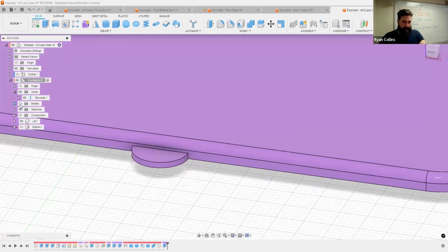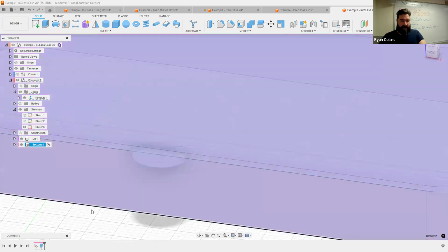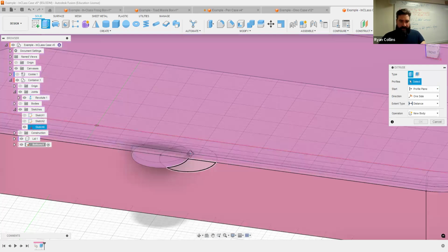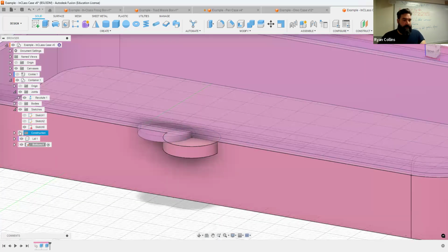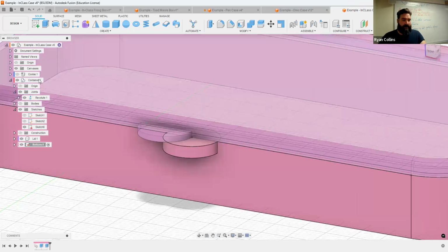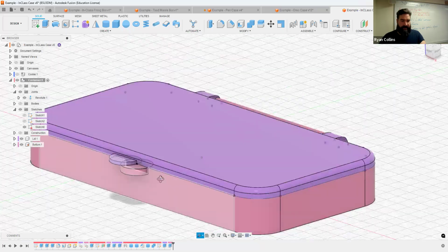Let's do the same thing. Forget which sketch I'm working from. There we are. Because it automatically hides. Let's unhide the bottom. Activate the bottom component. Do an extrude of that and the half round there. And let's extrude downward. Let's say 2 for that one just because. Okay. And now when we activate the whole container project, now those sketches, little thumb tabs are automatically on there.